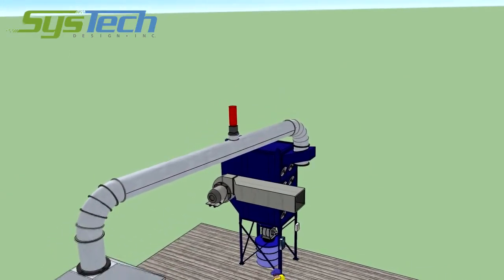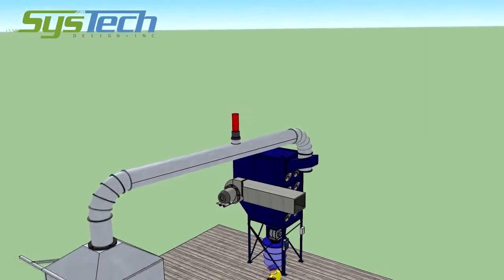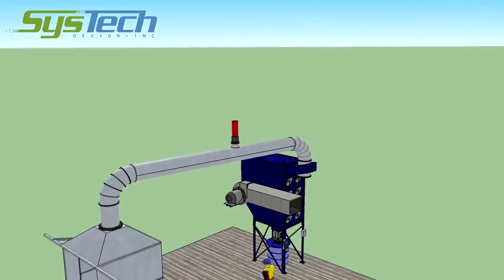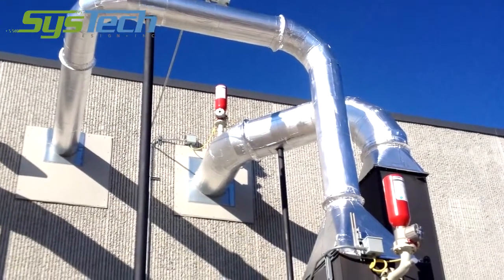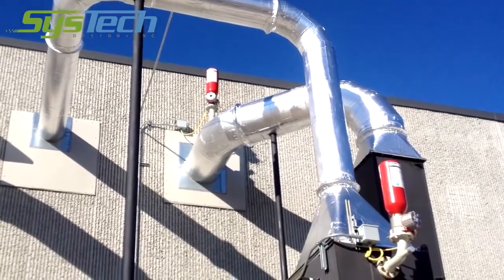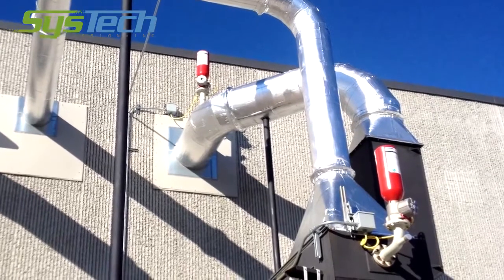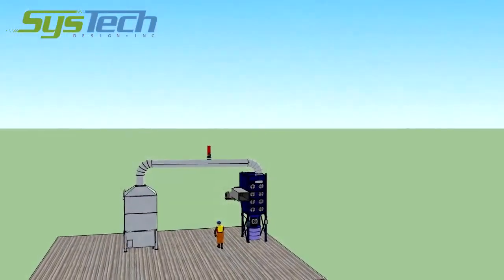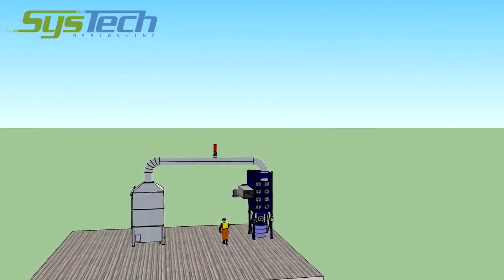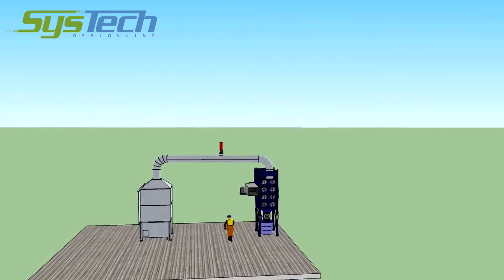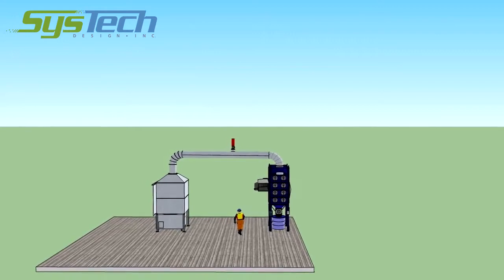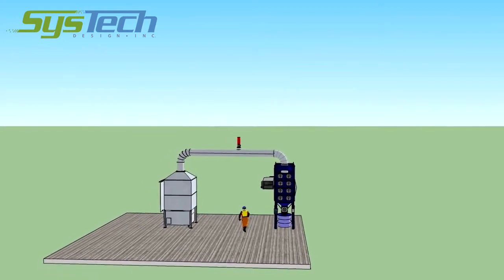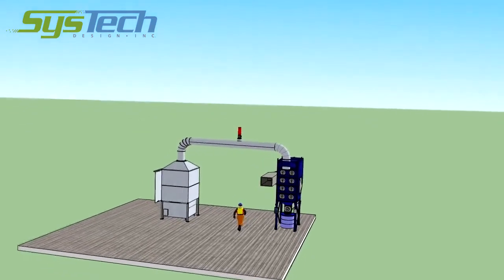Our video illustrates an explosion protection option which includes a chemical suppression system, explosion vent, and a chemical isolation bottle to prevent a fireball from going back into the facility. Because every application is different, it is essential that you speak with a specialist about your explosion protection and suppression needs. Having your dust tested is a good starting point for determining your facility's needs. The expense associated with this test is minor compared to the potential cost and impact that an explosion would have on your employees and business.